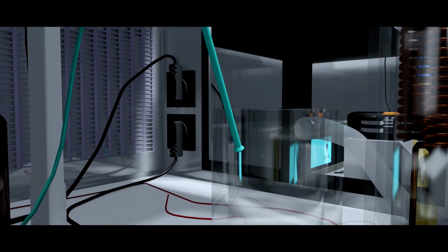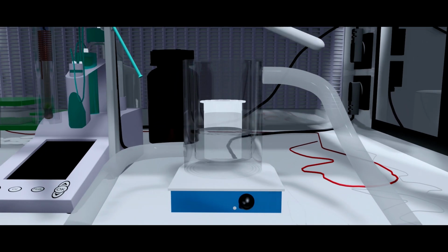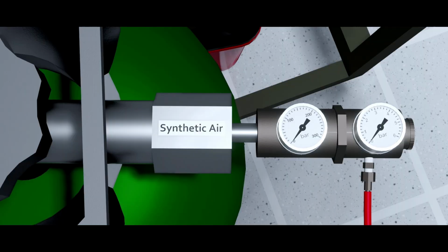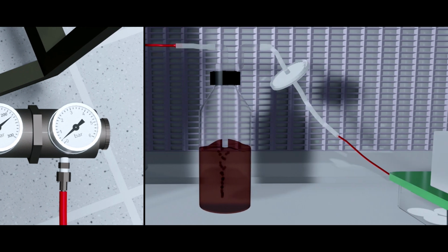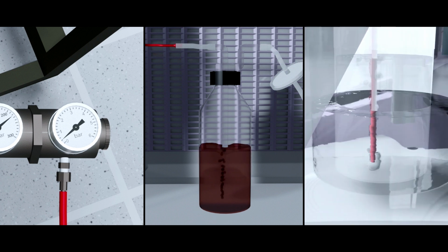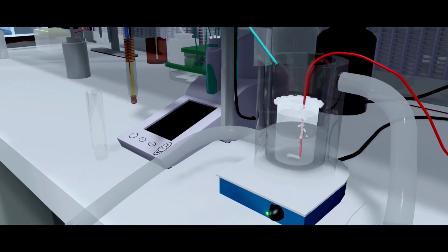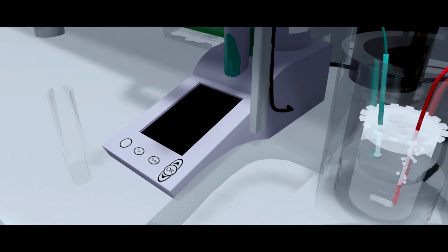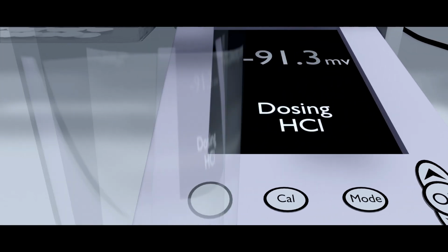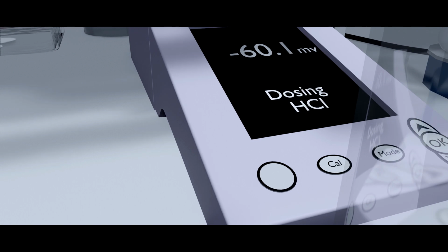The reaction vessel is inserted into a temperature-controlled environment. Pure air is pumped to achieve oxygen-saturated conditions. The air is cleaned using potassium permanganate and an air filter. Samples are aerated for 20 minutes before analysis. pH is controlled using an automated system.